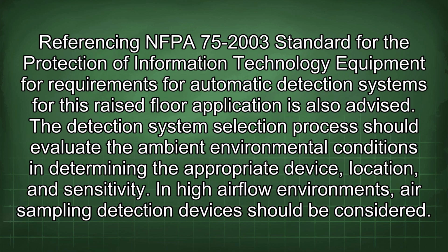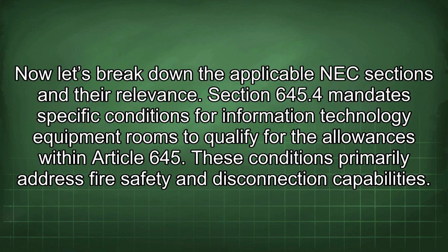Referencing NFPA 75-2003 standard for the protection of information technology equipment for requirements for automatic detection systems for this raised floor application is also advised. The detection system selection process should evaluate the ambient environmental conditions in determining the appropriate device, location, and sensitivity. In high airflow environments, air sampling detection devices should be considered. Now let's break down the applicable NEC sections and their relevance.